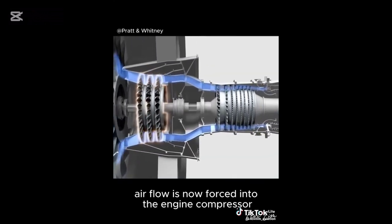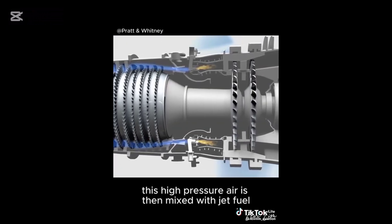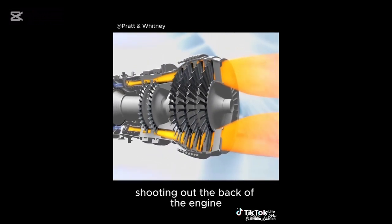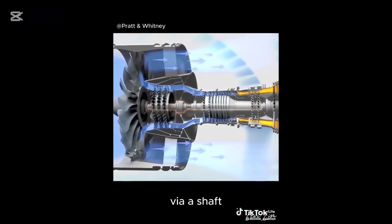Airflow is now forced into the engine compressor. Each compressor stage compresses the air and increases its pressure more and more. This high pressure air is then mixed with jet fuel in the combustion chamber and ignited, causing it to heat and expand rapidly, shooting out the back of the engine, producing some thrust. This drives the engine turbines. The engine turbines act as a windmill and convert that energy to power the fan via a shaft.